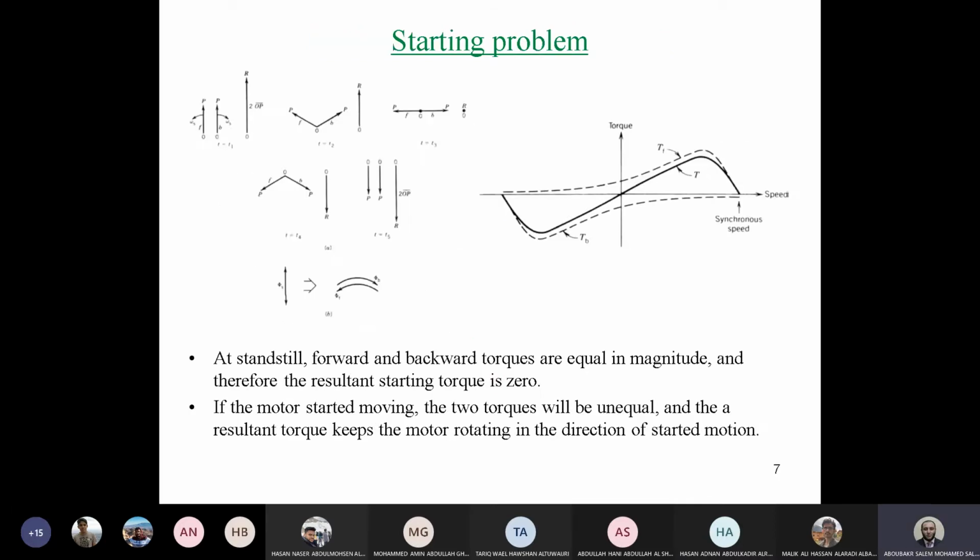So this is at one instant, and they will be summated together. When the vectors start moving, one in the direction of plus theta and one in the direction of minus theta, the resultant field will be the summation of the two vectors. So this will be the vector summation, which is this one, the resultant vector.